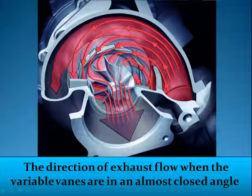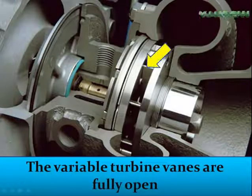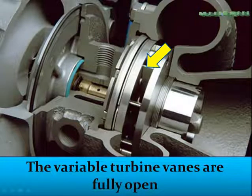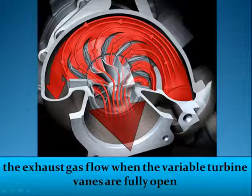The boost pressure and hence the engine torque rise as a result of the higher pressure drop between turbine inlet and outlet. At high engine speeds, the guide vanes gradually open. The required boost pressure is achieved at a low turbine pressure ratio and the engine's fuel consumption is reduced.